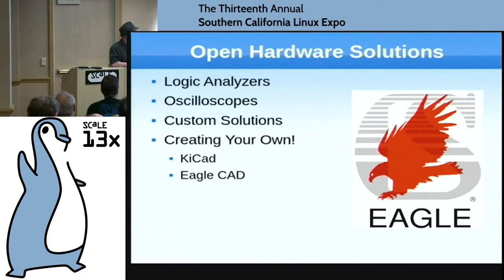The other one is EagleCAD. It is not open source, but it has been the choice in the hobby community for literally a decade because of some very basic items. First, you can get a limited version of EagleCAD for free with limitations. It only does 2 layers, and it has a maximum size of PCB you can design of 80 centimeters by 100 centimeters, I believe.